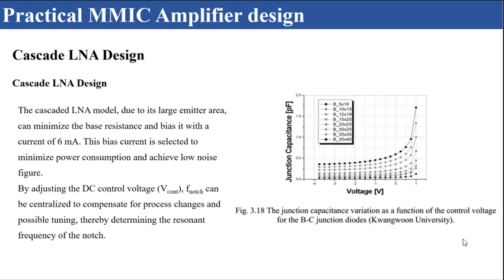By adjusting the DC control voltage, the notch can be centered to compensate for process changes and possible tuning, thereby determining the resonant frequency of the notch.